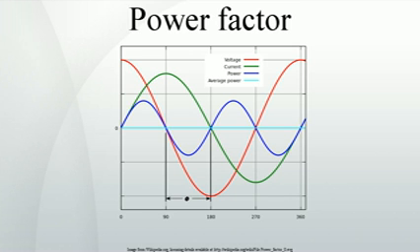The condenser's installation and operation are identical to large electric motors. Its principal advantage is the ease with which the amount of correction can be adjusted. It behaves like an electrically variable capacitor. Unlike capacitors, the amount of reactive power supplied is proportional to voltage, not the square of voltage. This improves voltage stability on large networks. Synchronous condensers are often used in connection with high-voltage direct current transmission projects or in large industrial plants such as steel mills.